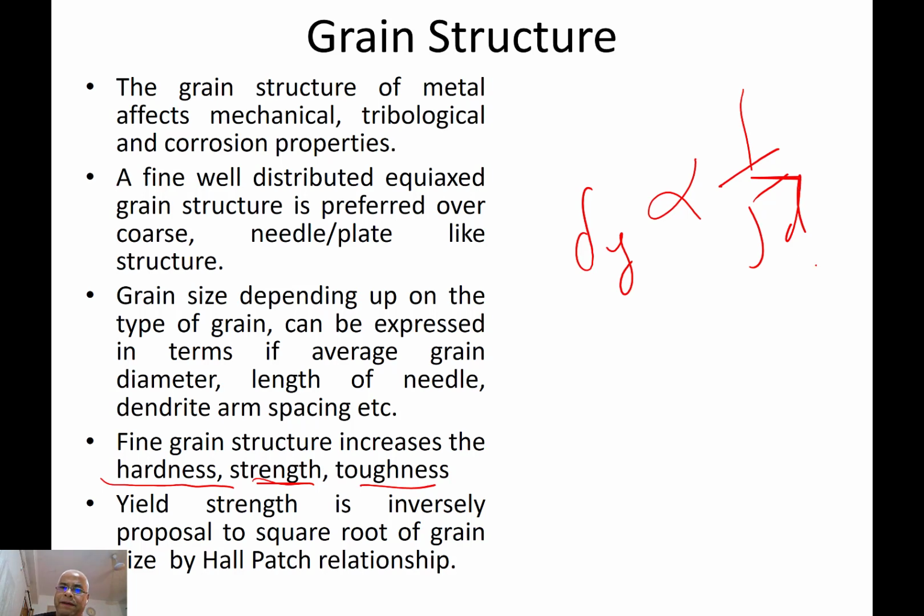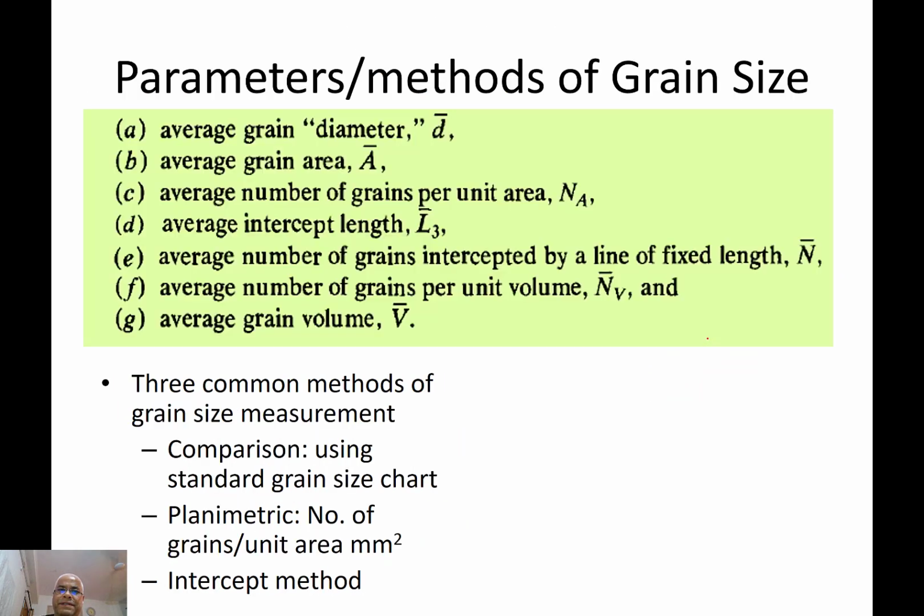So the finer the diameter, the greater will be the yield strength. Therefore, efforts are always made to have a finer grain size in the components.